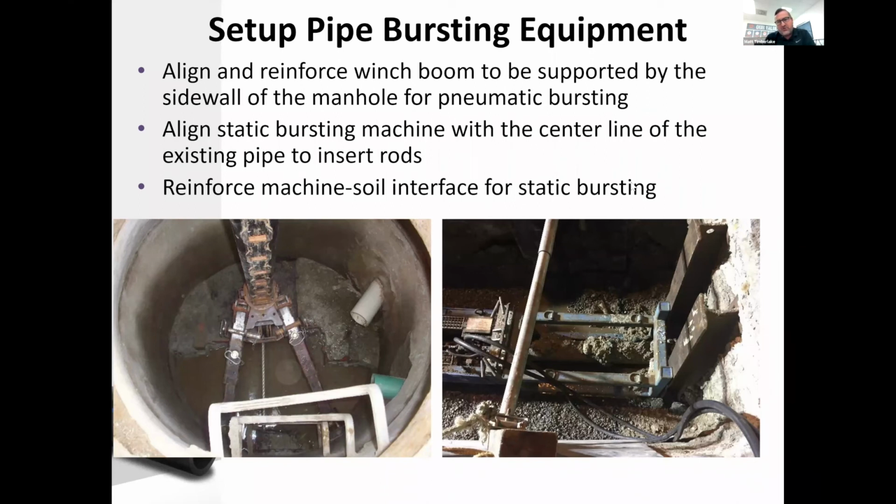And in this case, on the right, you see those 8 or 10-inch I-beams that are being used. Many times those are driven down into the ground just with the bucket of an excavator to shore up against. Sometimes you'll see a steel plate in there. But that's typically what the machine or the workhorse side of a pneumatic and static installation will look like. So contractors maintain entire fields of different inventory of equipment that they have. So whatever that pipe burst is, sizes, material type, they vary significantly on how they actually accomplish this, especially when we get into more and more crews as we go through.